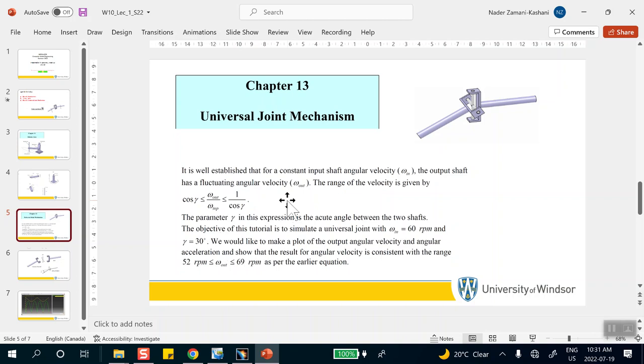Maximum speed compared with the input speed. So, are these legitimate to ask? Yeah, sure, right there. You're looking at it. If I give you the angle 30 degrees, you can tell me what the maximum speed of the slanted shaft is. The speed is variable, but the maximum speed is related by multiplying or dividing by cosine of that angle. But I'm not worried about that right now.